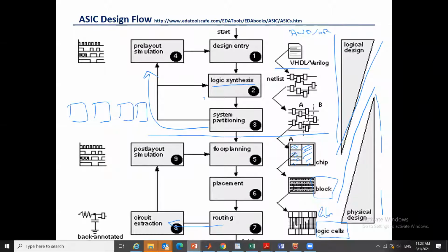And those parasitics that we take will affect the design. If I put this block on top of this block, the length of the wire is different than if this is placed here, and so the delay will be different, and therefore I may need to optimize my design and optimize my floor planning a little bit. So there is feedback really between those two levels.